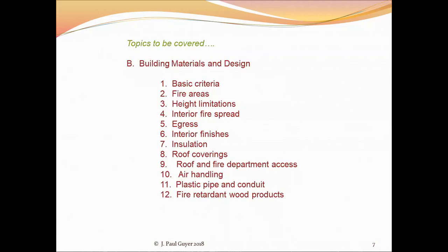Shut the primary air moving fan off, and then perhaps using a second fan and controls and dampers and this sort of thing, exhaust the air where the fire has broken out directly to the exterior. And that helps substantially to mitigate the smoke in other parts of the building.